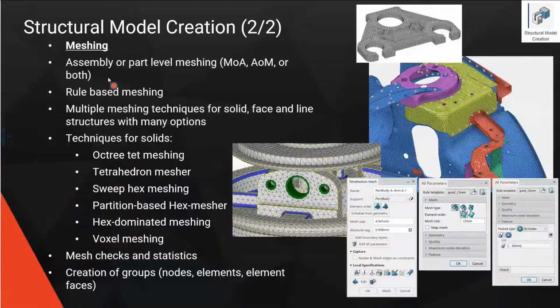Okay, also the meshing, it's great. It's very exciting. You can create a mesh of assemblies or an assembly of meshes. So you could just mesh one part, and then let's say you have an airplane with a bunch of struts in it, you could mesh the one strut and then take that mesh, that FEM model, and apply it through the whole body, the whole assembly. So you could take one FEM model of a part and use it many times, or you can just mesh the whole assembly, like we saw in the example.